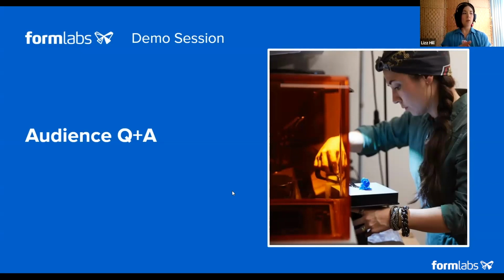If you're a jewelry designer looking to get into prototyping through 3D printing and production, you would essentially do all your modeling in your software of choice. You would then prototype, or set it up in PreForm the way that I showed you with the skull ring. You would then print it in castable wax resin or castable resin.